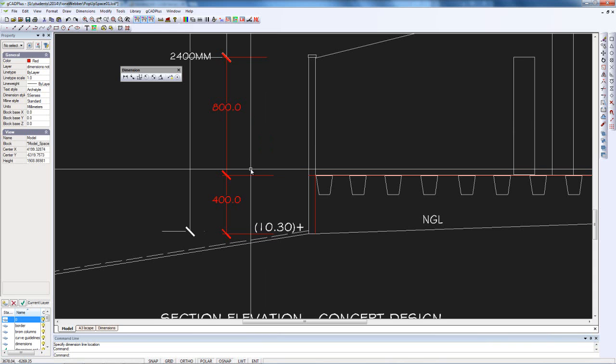I won't bother changing the color or whatever because I'm trying to make a point here. So the key issue is always let your dimensions come from the model. If it doesn't give you the number you expect, don't do the overrides, because you're trying to create an accurate model. You want, if necessary, to be able to send this model out to, say, a laser cutter, and you want things cut out of metal to your design. So it has to be accurate, very, very accurate.